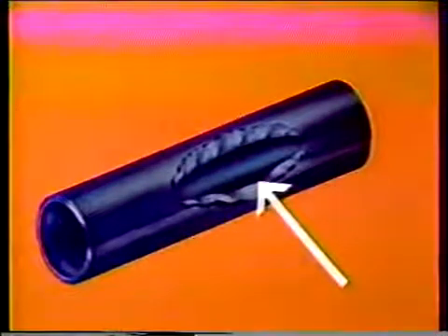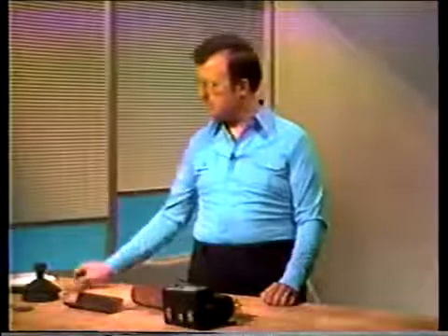Whenever a tube has split open, check both the inside and the outside of the tube before fixing it. This is important in determining why the tube failed. To inspect the inside of a failed tube, look through the hole caused by the rupture. If you can get to the inside surface of the tube, soft scale will be easy to see. It can be removed with a wire brush.